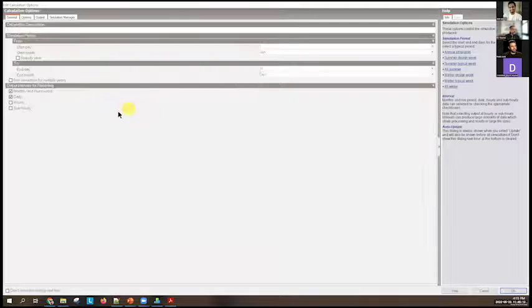Now I can do annual simulation, summer design week, all these, or I can give my own time. What I want to do is run an hourly output. I don't necessarily want a daily output. I want hourly and monthly outputs.